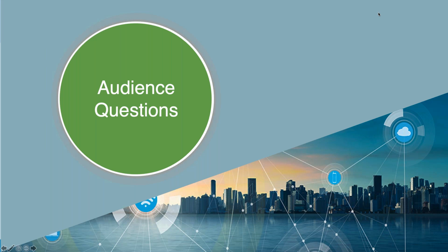One thing to keep in mind for reliability is that if you were to have a power outage while you're updating the kernel, or if you were to see some network latency issues, you could lose connectivity to your device during a critical update. So we're also working on features that will have redundant flash capabilities so that even if you lose power, there's a recovery state so you don't lose connectivity to the device. But yes, over-the-air cellular is one of our key requirements and care-abouts.